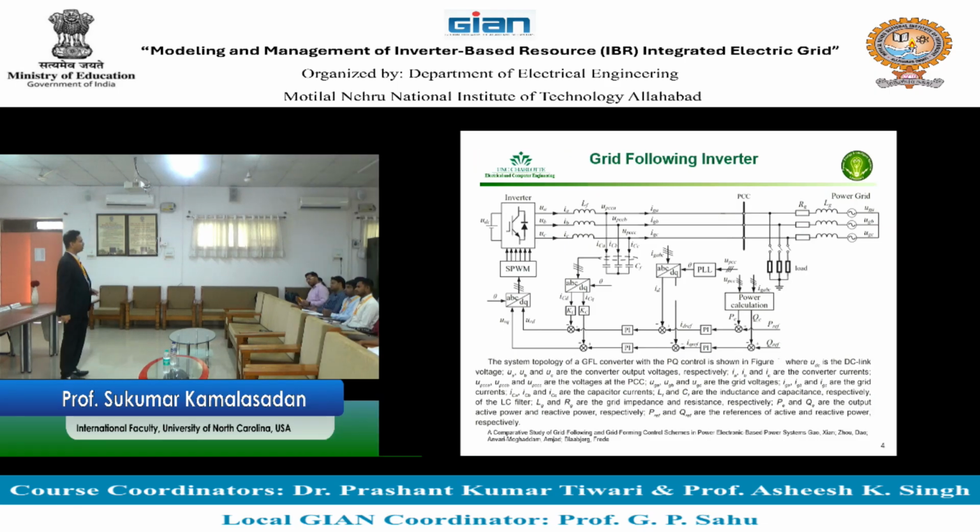To work on the case where DC is not stable and see the effect on the AC side, you need to have the DC side modeled, meaning you need to model the PV farm, the wind farm, whatever, and then find out the change on the DC side appropriately. Then only work on it.